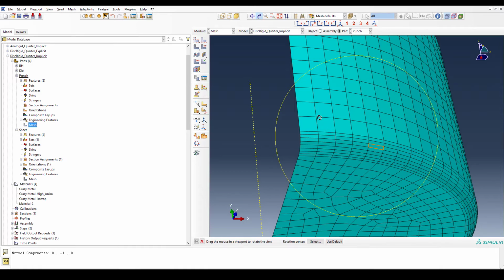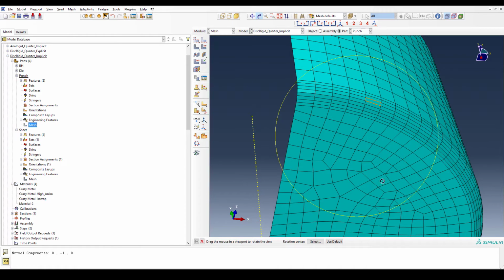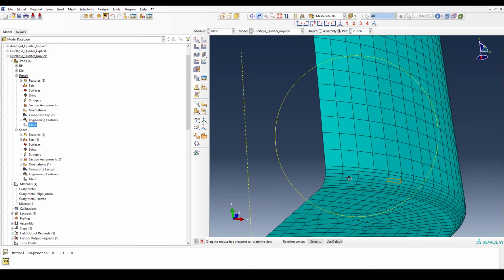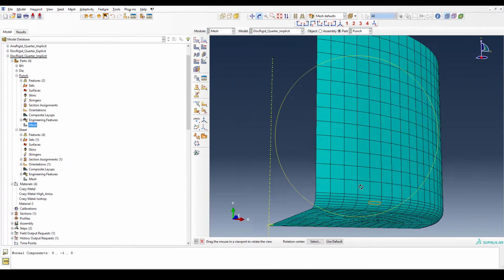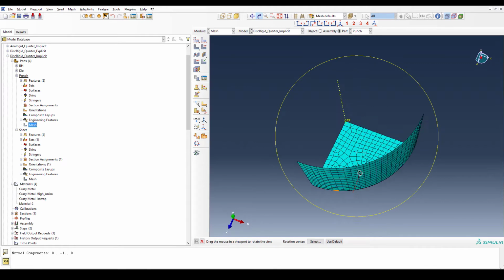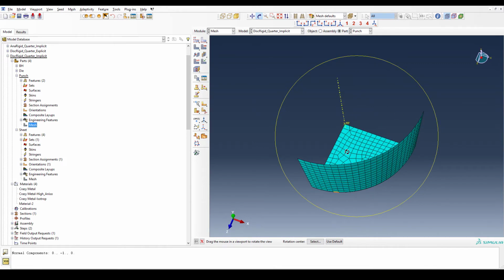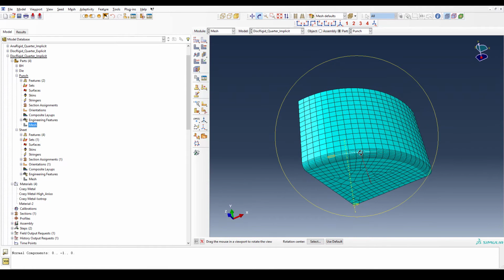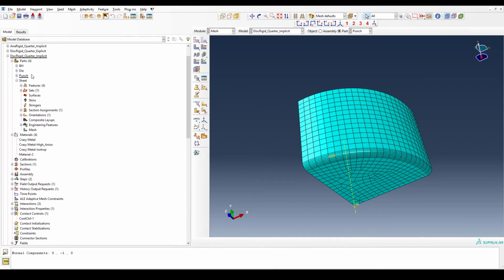The sheet will be here, with barely any movement of the particles of the sheet underneath the punch. However, it will bend around this corner, so having a good resolution of this edge is fairly important. The same holds true for this radius, which is the discretization of your circle, so to speak. So don't make it too coarse, because that might greatly affect your results.